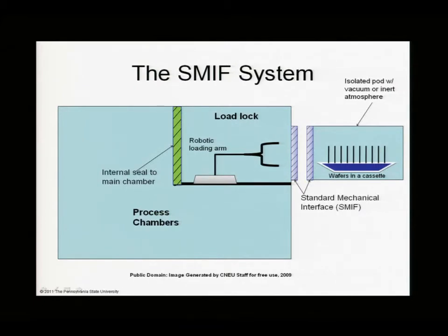So up comes the SMIF, that's this. It docks here. There's no leakage. The sample gets transferred into here. This is pumped down by the vacuum pump, and then the sample's passed in, and the processing is done in these workstations or workstation. Very controlled environment. And then when the processing is done, it comes out, comes into here. Another SMIF box is docked here, perhaps the same one. The SMIF box and this region are pumped down again. The samples come through, go into here, and then this closes, and you're ready to repeat the process.